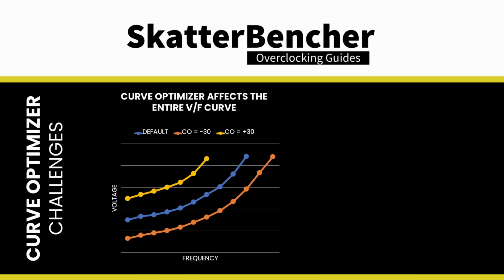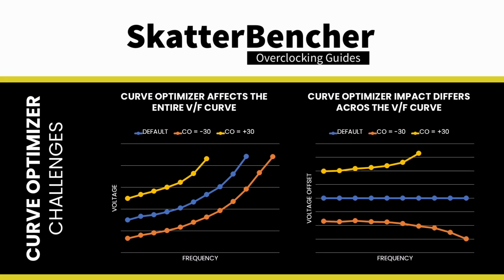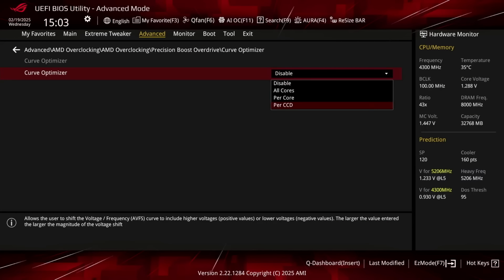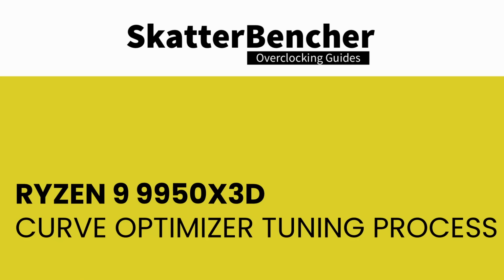However, there are a couple of caveats to tuning with Curve Optimizer. One, Curve Optimizer impacts the entire voltage frequency curve, so it affects stability across the entire range of operating frequencies, from 600 to 6000 MHz. And two, the same Curve Optimizer value impacts differently across the curve. Curve Optimizer is available on a per CPU, per CCD, and per core basis. The manual tuning process for Curve Optimizer can become quite convoluted because the tuning process spans a wide range of workloads, going from heavy all-core workloads all the way to light single-threaded workloads.